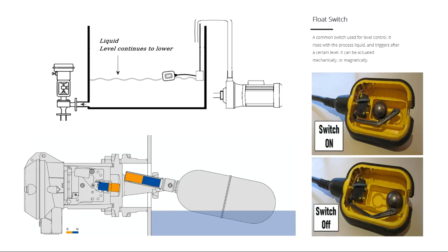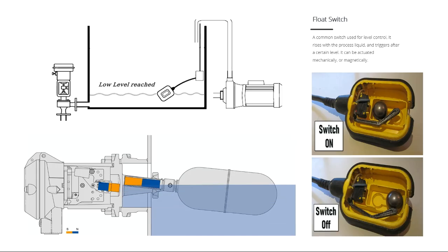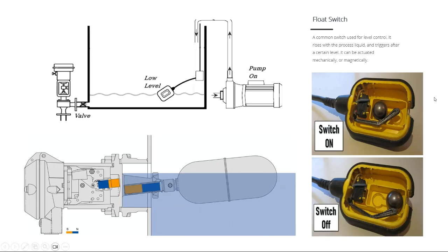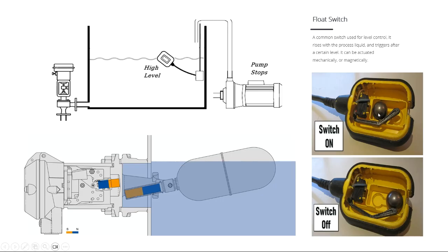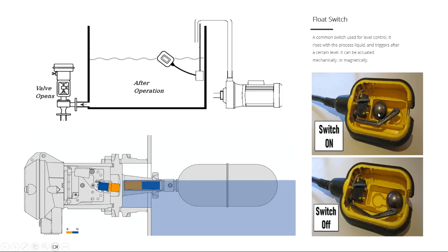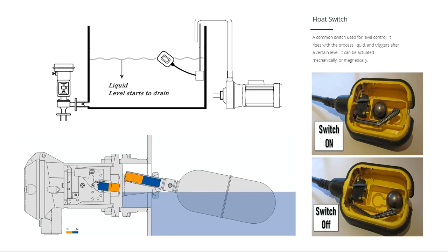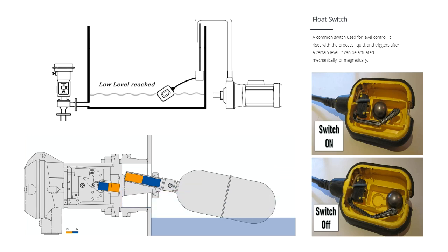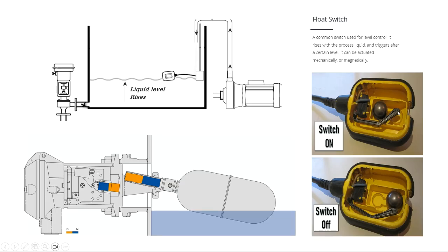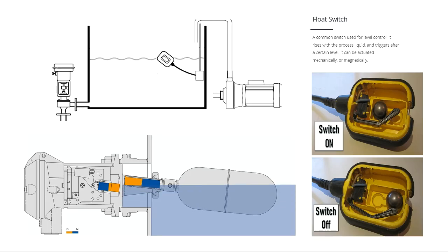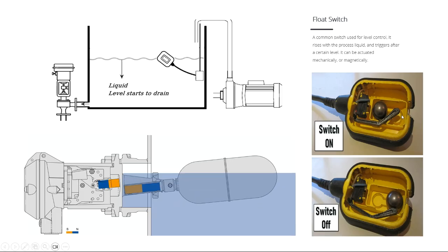As the liquid level rises, so will this sensor rise. And inside there is one metal ball. Depending on the orientation of this sensor, it will give a signal of on or off. Okay, it will use gravity and the concept of buoyancy to give the signal of level switch.